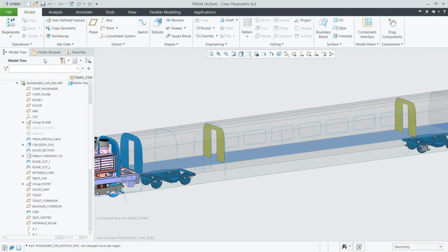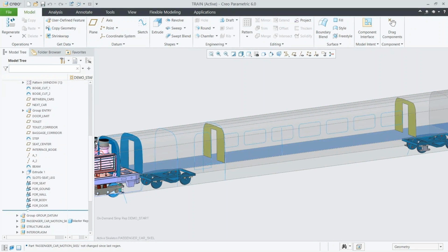So we can start using some of this information to create the rest of our assembly, right? So if we've laid out, okay, from a top-down design, this is what we want our assembly to look like. These are the boundaries we care about. This is probably what would need to be changed in the future, if we need to change the profile or the size or the shape, or where the windows are placed or the doors or the floor. These are the things that we care about, and these are what we want the rest of the subassembly parts to reference. Because if everything references these, then when we change them, everything can update automatically into a new position or a new configuration.